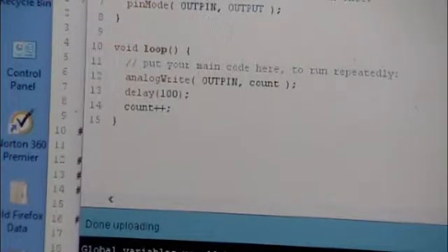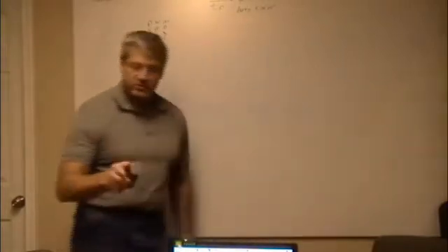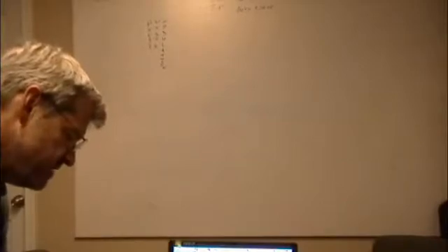So the next thing, since we're using Arduino, if you're using an Arduino, they have a built-in command in their libraries called analog write. And I think we touched on this at one point, because we were looking at our Arduino boards and seeing the pins that have the tilde on them. A pin with a tilde, which on an Uno is pin 3, 5, 6, 9, 10, and 11. Those are the only pins that you can do an analog write on.